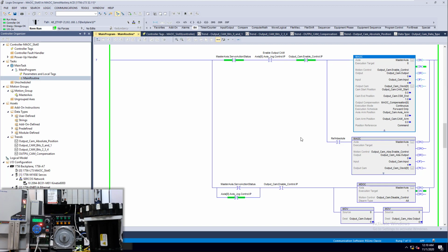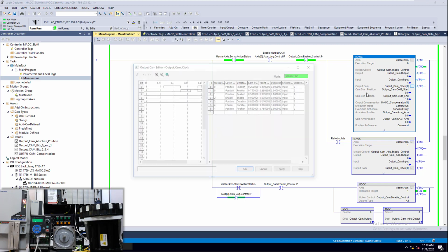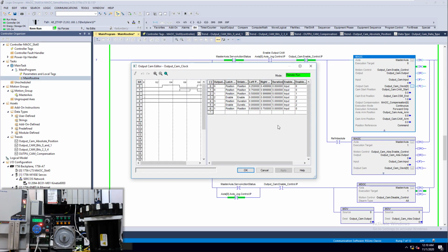It takes your servo position that you have programmed, and you are able to set a command position or even build a cam. You can build a cam and load the cam differently every single time this thing fires. You're able to do that. And to use the cam editor, you just simply go in here and edit this however you want to.